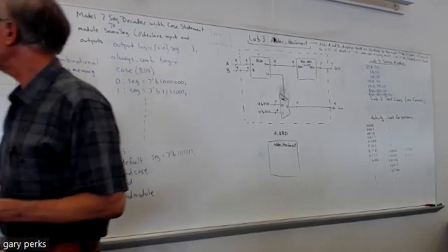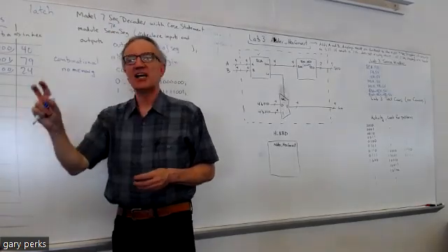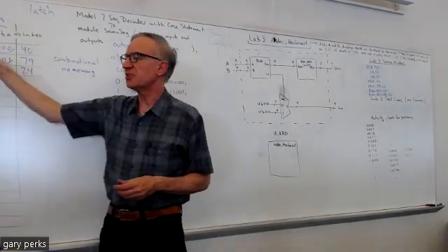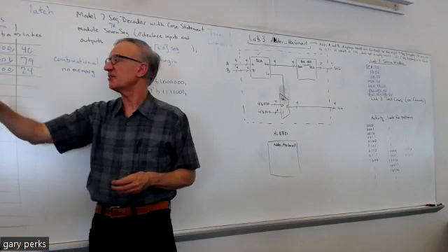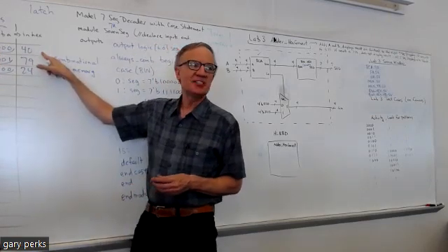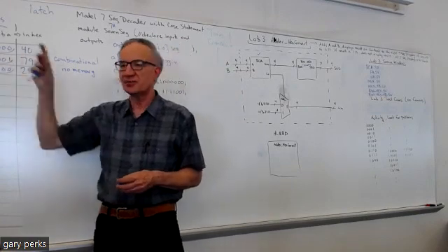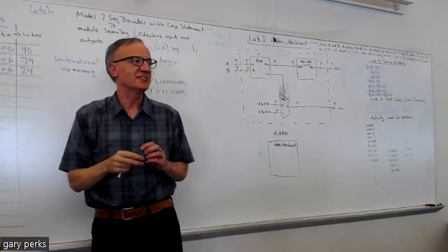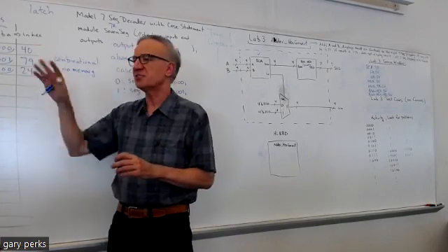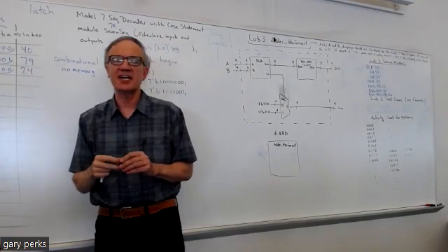Okay, so I mentioned that because when you go to verify that your decoder is working, if you're looking at these 16 test cases on your timing diagram, if you change the base to hex, then all you have to do is look for these here, as opposed to looking at the binary bits and making sure they're right. Okay, so it might be more convenient just to put it in hex.